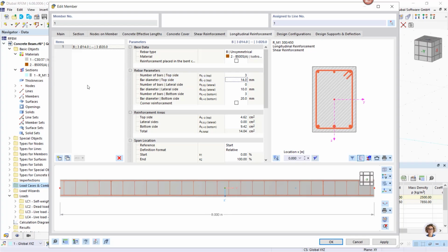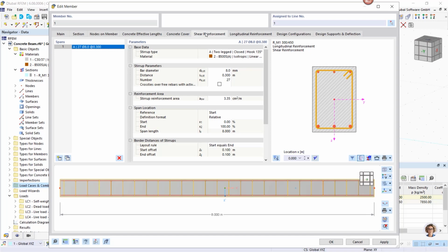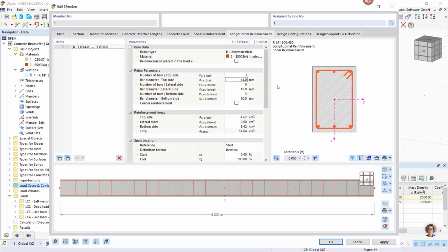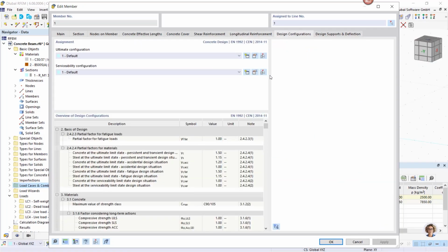Yes, and again, it also finds the reinforcement material, and we can also see here the reinforcement area as information. Then you can check whether it fits the values you would like to have. And the same was available here also. You see also the area for the stirrups. This is the reinforcement we want to use now in our example. I go and apply once in a while, and then we can go to the next register.